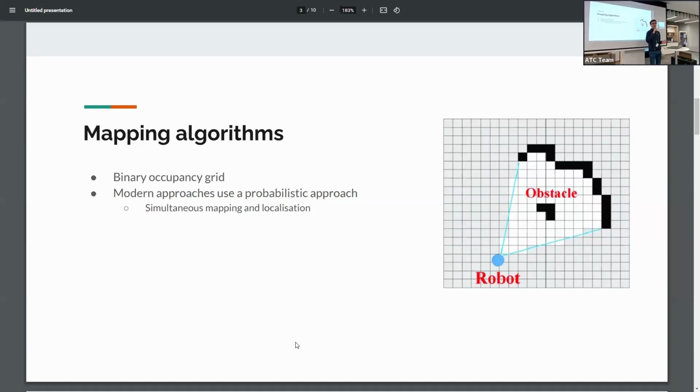So what types of sensors do we use? The first and one that I think everyone thinks of is a LiDAR sensor. So these are extremely accurate, but they only work in a single plane and they are extremely expensive. In my university days, I had to make one of these robots and my LiDAR sensor set me back about 3,000 Rand, and that's the very, very low end. As these robots get a little more technical, these sensors will cost you tens and tens and tens of thousands because the accuracy is that important.